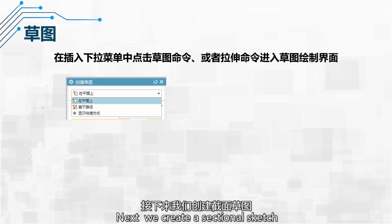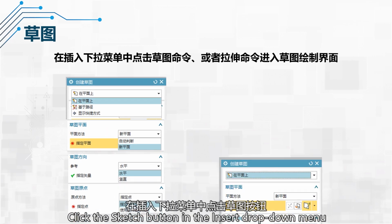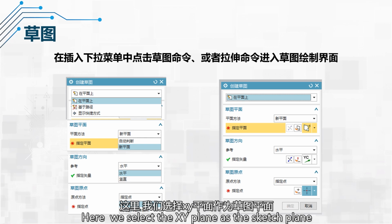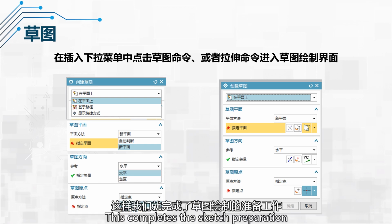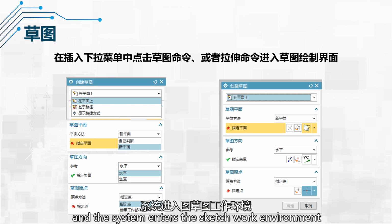Next, we will create a sectional sketch. Click the Sketch button in the Insert drop-down menu, or click Sketch Drawing under the Extrude or Rotate commands. Here, we select the XY plane as the sketch plane, specify the vector direction as the Z-axis, and set the sketch origin and coordinate center point. This completes the sketch preparation. Click the Confirm command and the system enters the sketchwork environment.